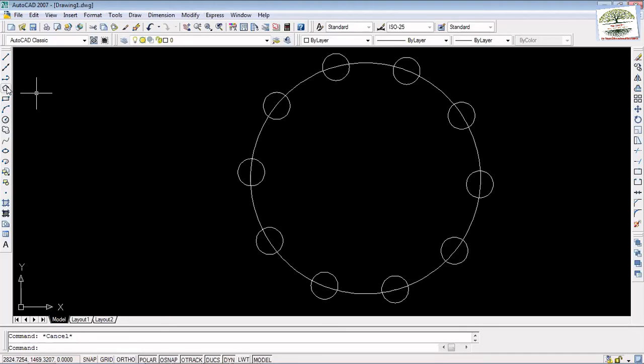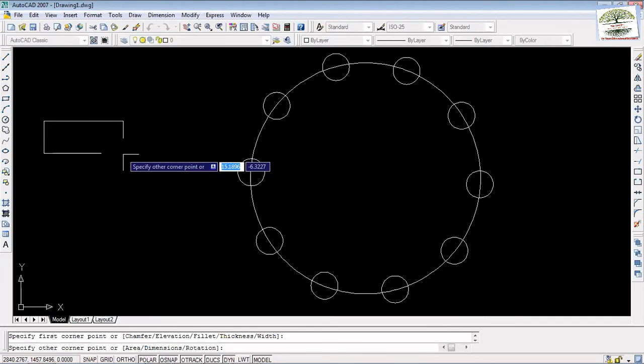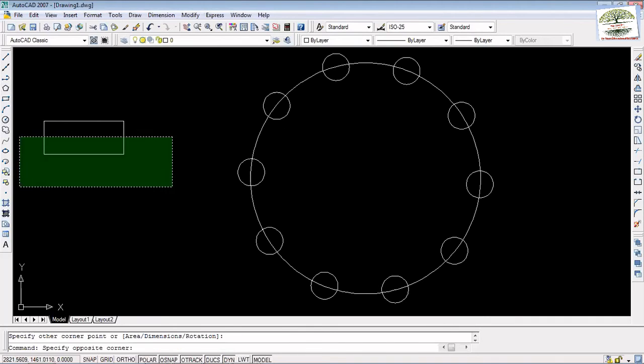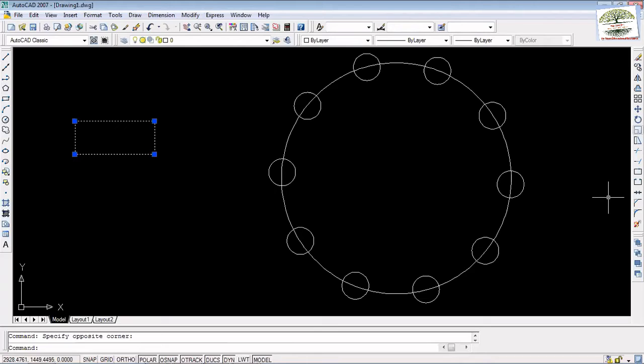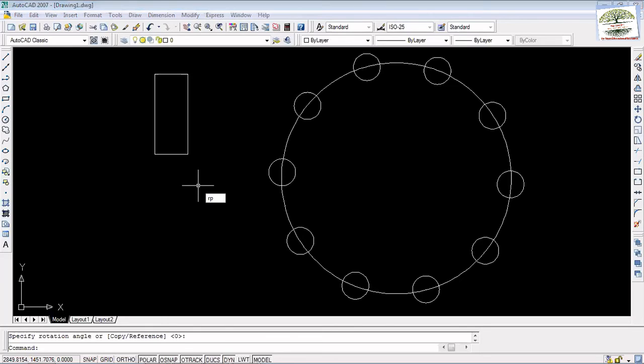And now this is the rotational part. This is the best example to show you the rotational part. See, I'm selecting this, I'm going to the rotation, select this, make it happen. This is done. If you'd like to go for ROTATE, type RO, space bar, select object, left click, done, right click.